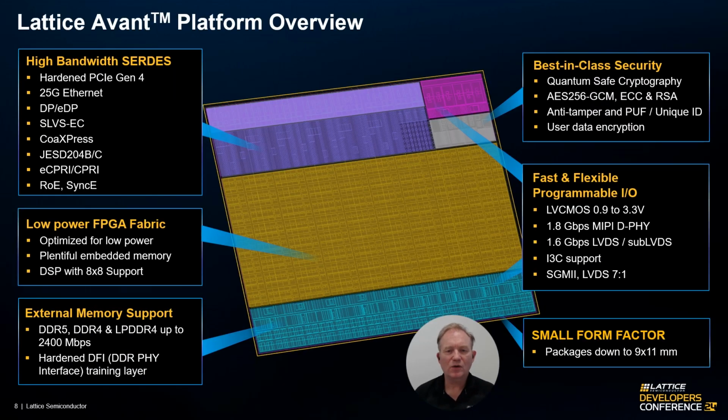So let's take a quick tour around the Lattice Avant platform. At the center of every Lattice Avant device, shown by the large gold block in the center of the diagram, we have a low-power FPGA fabric. In addition to supporting low-power logic implementation, the fabric has plentiful embedded memory blocks and DSPs, which incorporate the ability